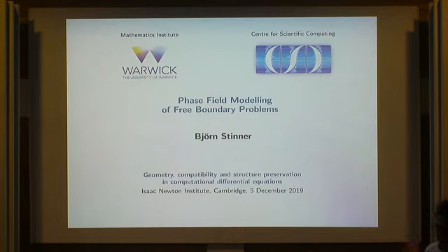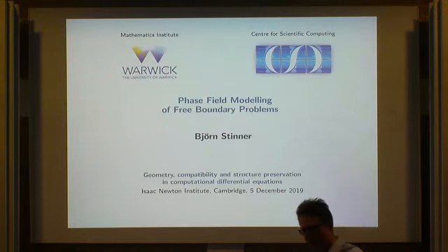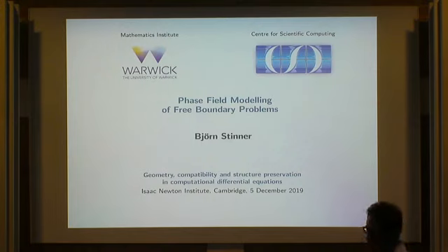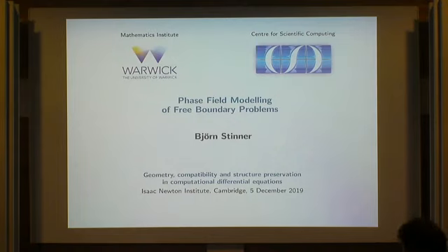I'm also working on computational free boundary problems, but I want to talk about a specific way to approximate them. This phase field methodology can be seen as a way to smooth the free boundary problems, so that the numerical computation of solutions becomes a bit easier. I can then resort to more standard methods. We will be using adaptive finite element methods, but you could resort to other techniques as well. People have been using finite difference methods in material science, and I've also seen computations using NURBS and splines, using isogeometric analysis. So the computations become a bit easier thanks to this smoothing step.